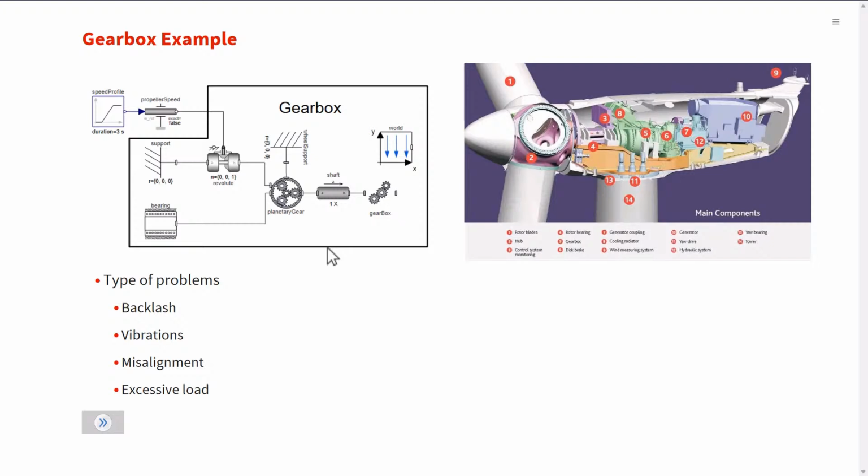And we will now examine the Acciona AW100/3000 gearbox, a key player in wind turbine operation. Identified here is item number 5. It is a complex assembly featuring a planetary gear and a 3-stage gearbox. So this is the gearbox we are looking at inside this Acciona, and this is how we model that gearbox using rotating machinery: a planetary gear, a 3-stage gearbox, and one shaft in between.